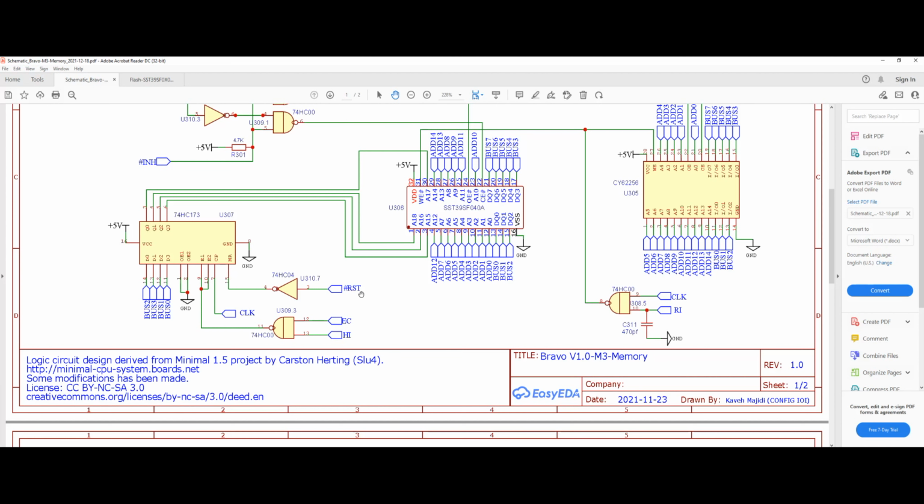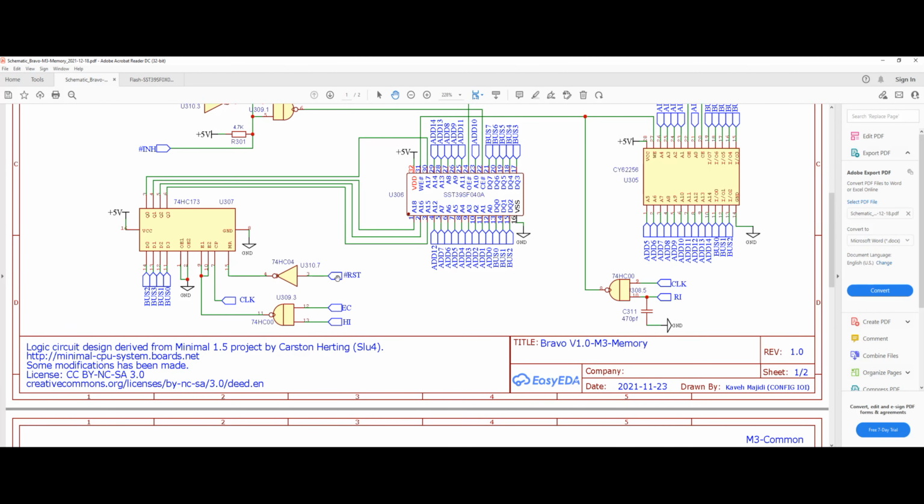This signal is connected to multiple chips in our computer, and whenever we bring this line low, it will reset all of those chips to, let's say, 0. However, in the case of this specific chip, it is active high, and that's why we need an inverter, just to be consistent with the rest of the computer. When this line goes low and everybody else is resetting, this inverter makes the signal high, and of course this chip will be reset.